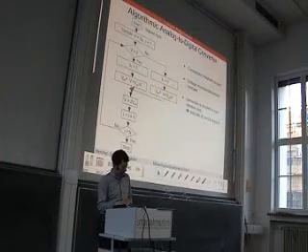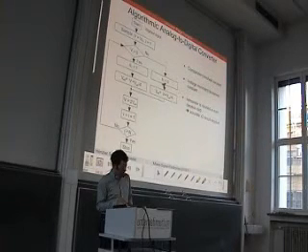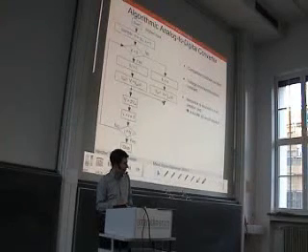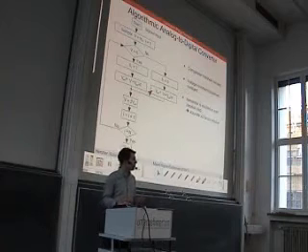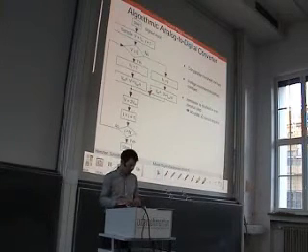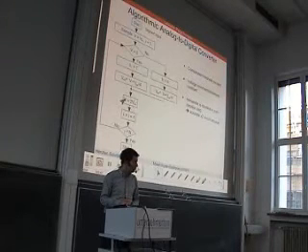If not, which means if V was smaller than 0, then we set the respective bit to 0 and we increment the internal voltage. After decrementing or incrementing the internal voltage, we have the remainder, and we amplify this remainder by a factor of 4.